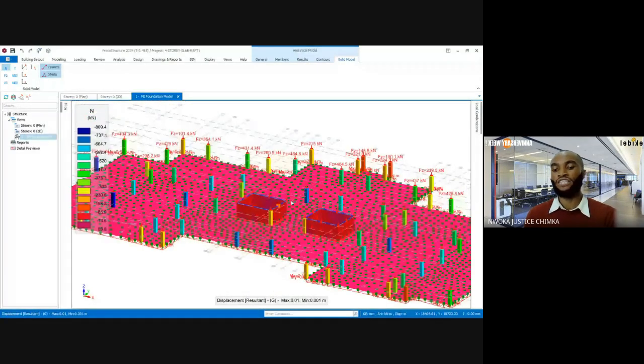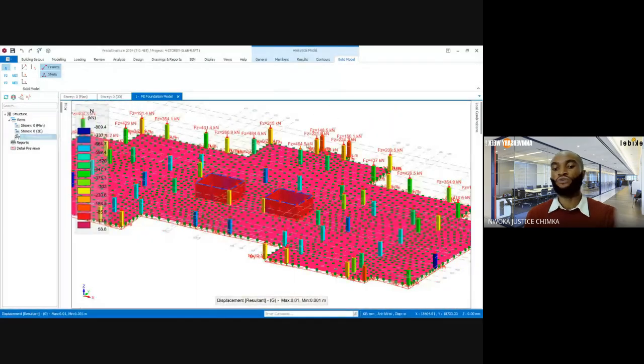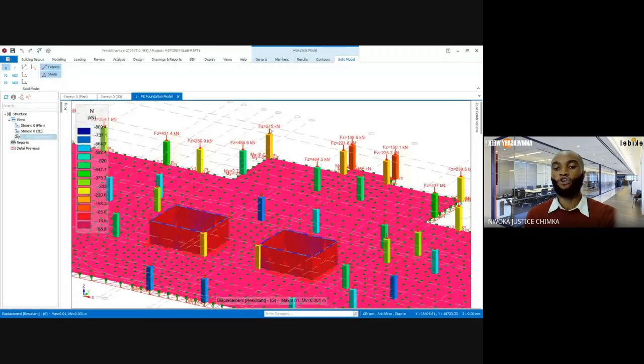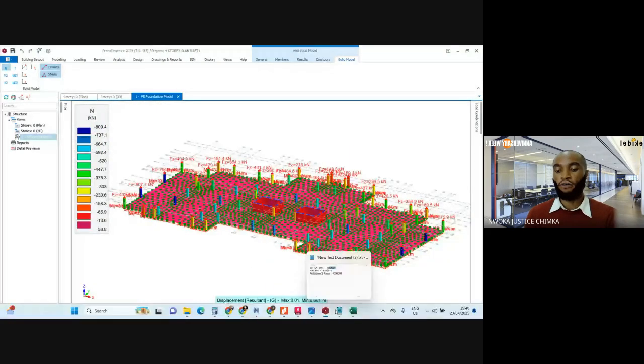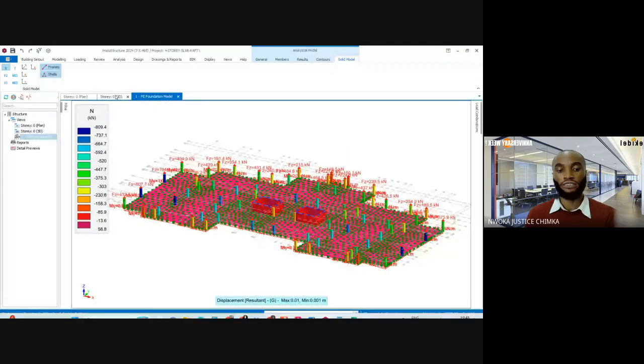While these ones that are showing green, yellow and all that, you can choose to ignore them. They have lesser column loads, which the T16 at 150 bottom reinforcement can carry. Now, if anyone is going to require punching, you will see it based on the column load and also on that contour. And from the punching calculation that we just did, in here, back to this place.